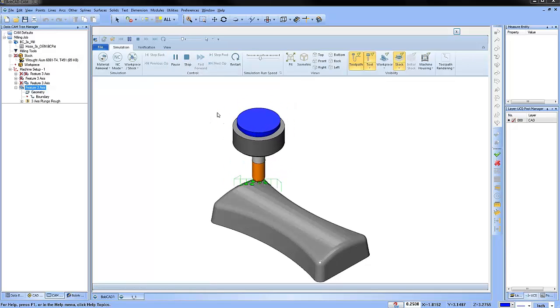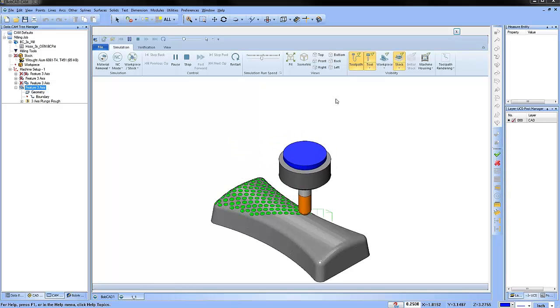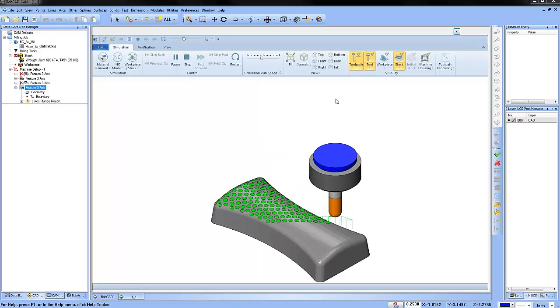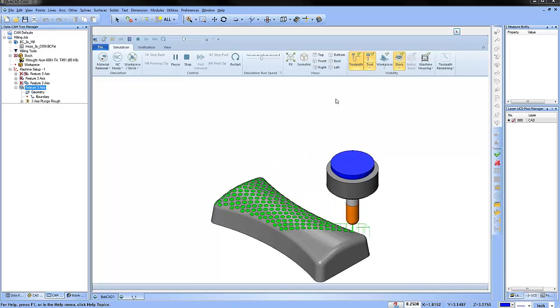Some of the machines don't have as high spindle speed range, and plunge roughing or drilling out material has just been a very common way in which it's been done. All the force is pushed down versus side force, so there's a number of different benefits for it.